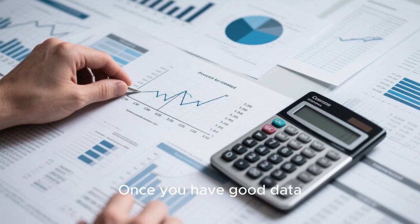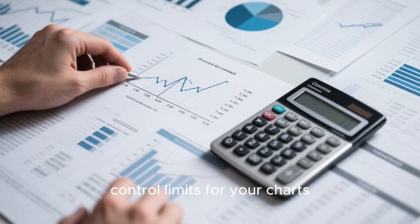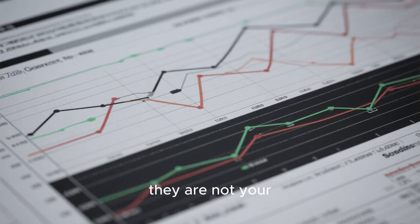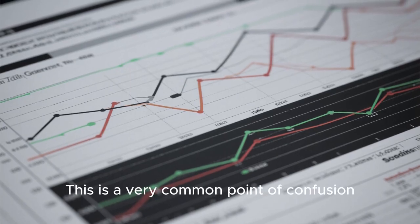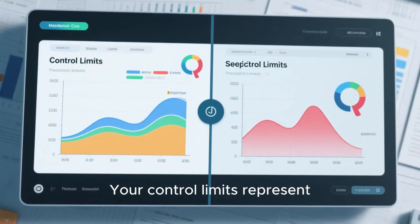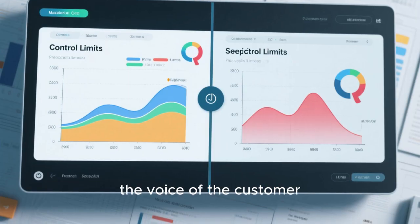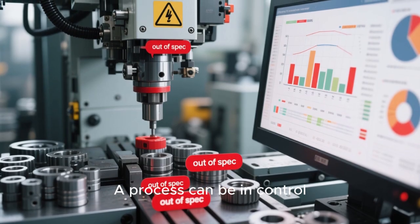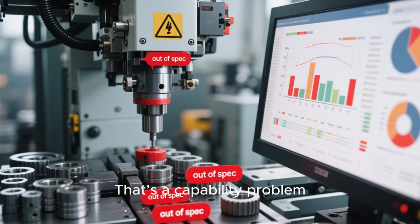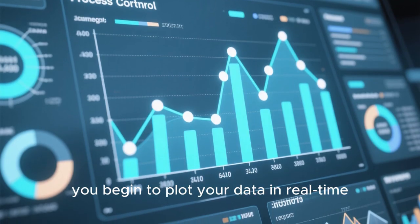Once you have good data, you can calculate the center line and control limits for your charts. These limits are calculated directly from your process data. They are not your specification limits. This is a very common point of confusion. Your control limits represent the voice of the process, while your spec limits represent the voice of the customer. A process can be in control but still produce parts that are out of spec. That's a capability problem.